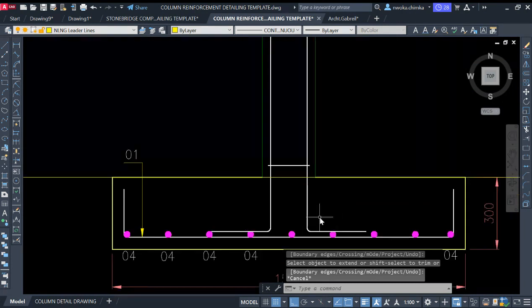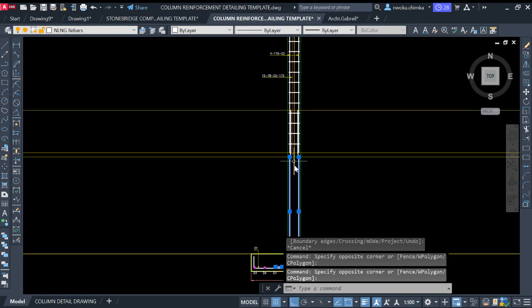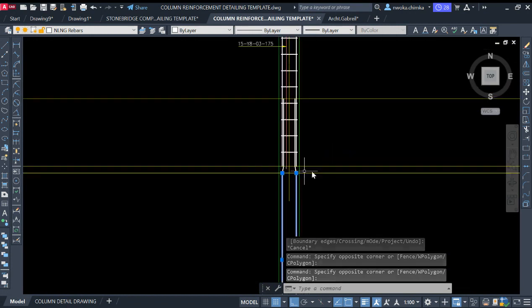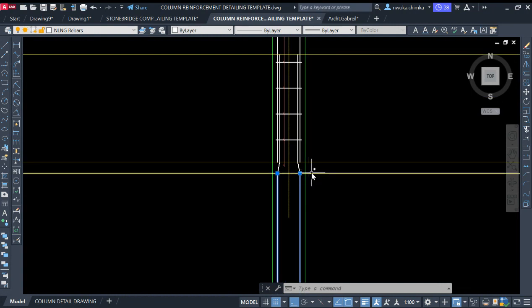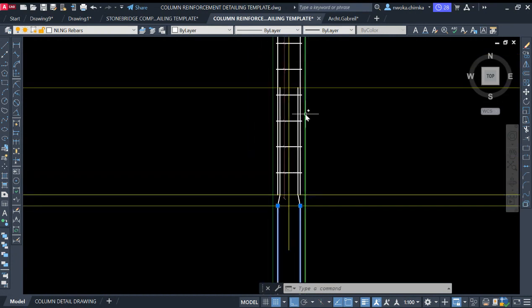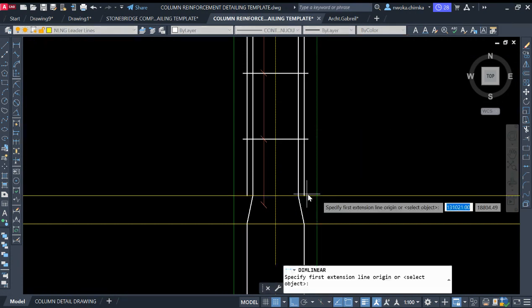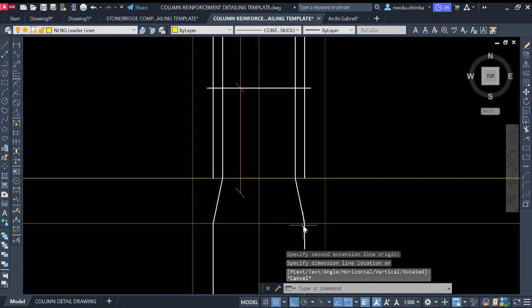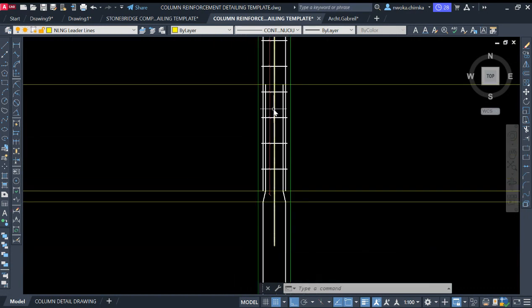So you can now see that this is the column reinforcement coming from the foundation. When it comes to this level of DPC, let me say top of concrete, you can see it here. It now cuts, which causes a lapping of 800. This is the kicker. From this kicker point of 75, it forms a kicker which will show a little deviation and then go upward. This is how it will be on the construction or at sites during the construction.